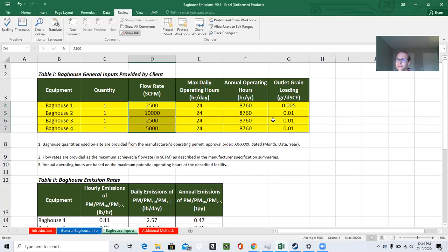If you have it regulated on a pound per ton basis, then when a change in your industry happens and there's a huge demand for more pasta, you're not legally allowed to increase your throughput because you've been limited on your permit to a specific pound per ton. Your emissions have been specified as a total, say, 200 tons per year, or more realistically, say 5 tons per year for your baghouse.